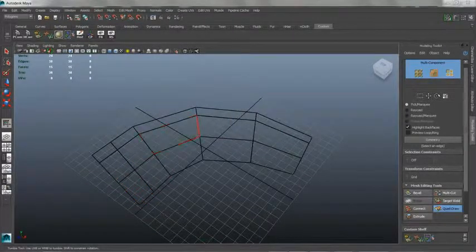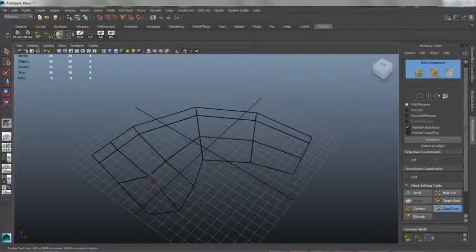In addition to creating polygons, the Quad Draw tool can be used to insert edge loops and merge polygons. Removing faces and replacing them is as simple as drawing new dots. With any transform tool, you can quickly tweak highlighted components along any axis using the middle mouse button. Tweak mode lets you quickly transform components without making a selection or using a manipulator.